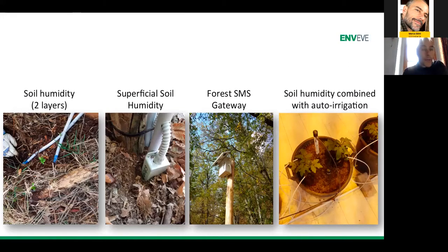You may have a very good sensor, but install it improperly, and the data you gather would not be good. It is important to take sampling at different levels in several applications, maybe 2-3 levels, depending on the plant and on the soil condition.